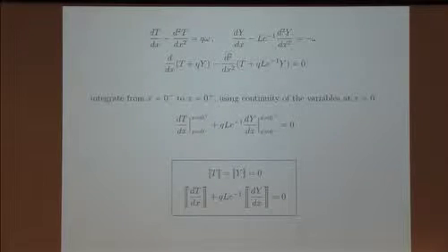Then, because the solution is continuous, which means that the jump in T across the reaction zone and the jump in Y across the reaction zone is 0, having the same value on both sides, the first derivative terms drop when you integrate. You get T plus qY, and the only contribution comes from the term which is written here. That immediately tells you that there is a relation between the energy flux, actually the net energy flux out of the reaction zone, right?